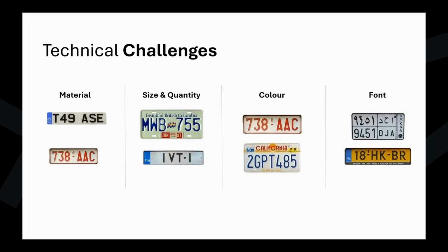Of course, conversely, we actually have some states which assist ANPR systems in order to work. So, for example, we've got this example of a Dutch plate, and you'll notice on the R at the end of the plate there, they've cut out a little notch at the top, and that's so that even if there is some dirt or dust, as mentioned, partially covering the plate, that R has a better chance of being picked up versus a B or an 8, for example. So it's all very varied, and certainly specification and installation design has to take all of that into account ahead of time.